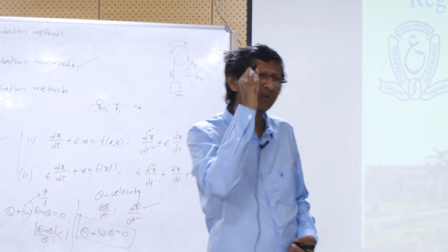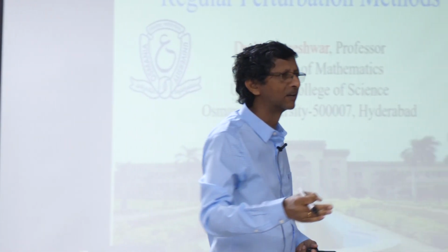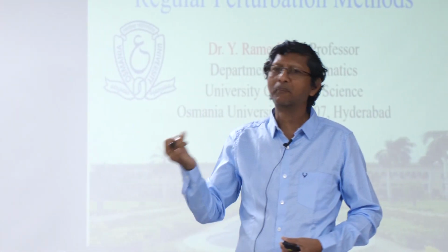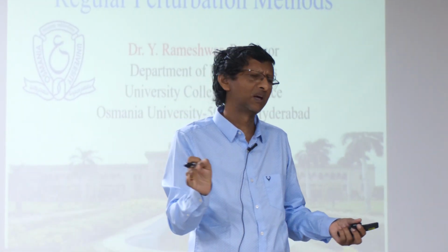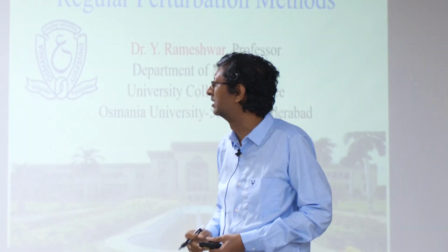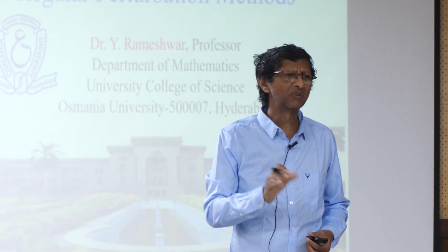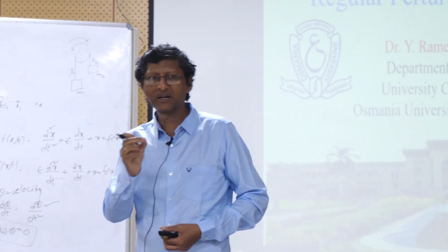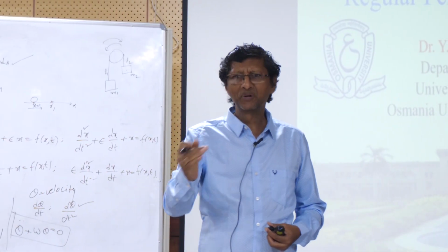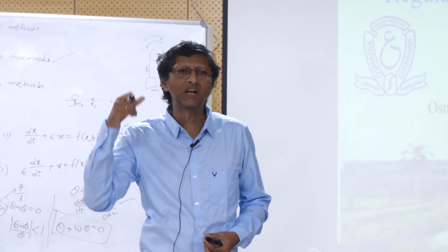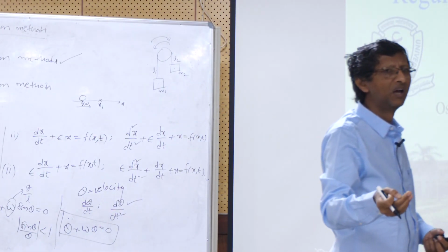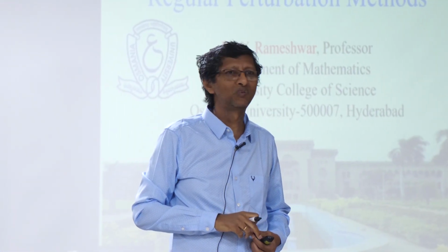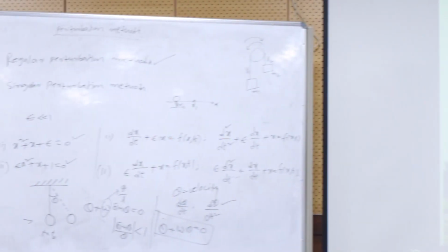So with the help of that, we have a lot of problems available in fluid dynamics like plane Poiseuille flow, plane Couette flow, and Poiseuille flow and Couette flow combinations. One can solve the problems using the methodologies given. Closed form solutions we can get, but if it includes small parameters, for example, the Reynolds number, right? If the Reynolds number is very large, then 1 by R is very small, and if those types of terms are included, then how to solve those equations? For that, we take the help of the perturbation method.